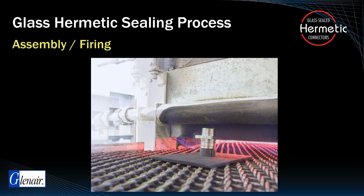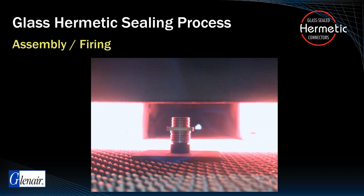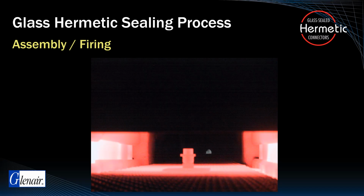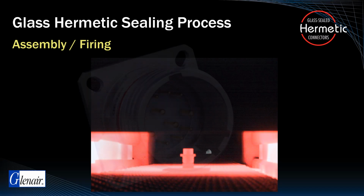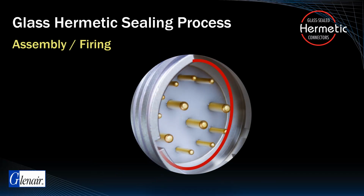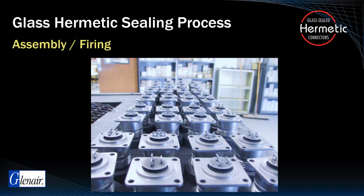The assembly is then run inside a controlled temperature furnace and subjected to a gradually increasing temperature of approximately 1,700 degrees Fahrenheit. At the sealing temperature, the glass melts and fills all voids between the contact pins and shells, forming an extremely robust mechanical-chemical bond, due to both thermal expansion properties and molecular level interactions between the glass and metal. The assembly is then gradually cooled.